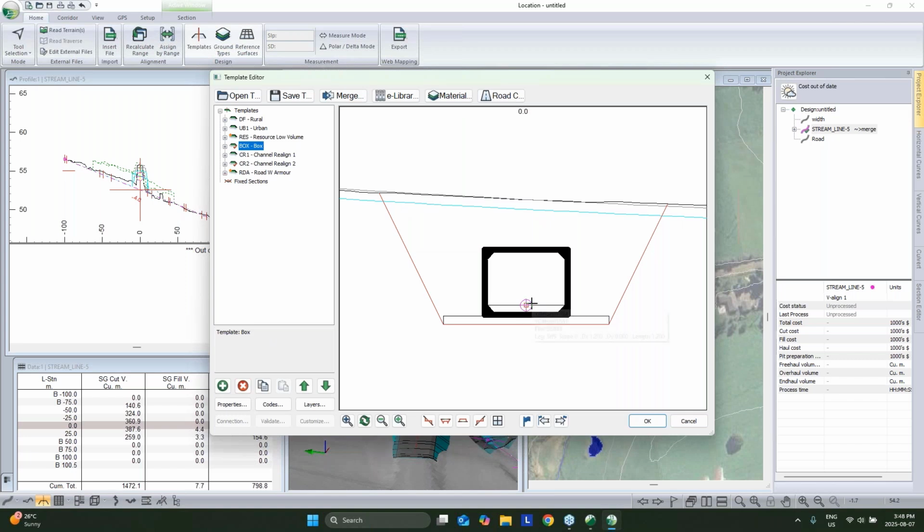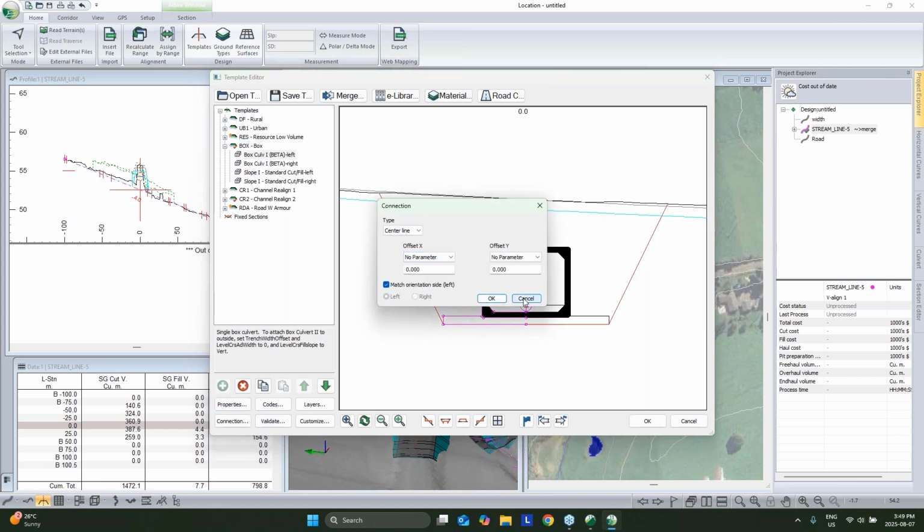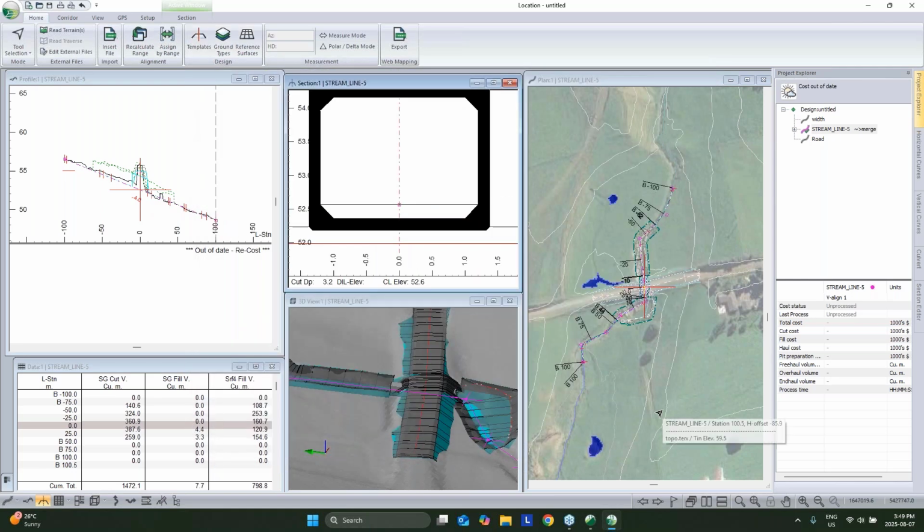So of course, if we want to help ensure fish passage, we probably aren't putting the center line on the bottom of the outside of our structure. So here we've got it embedded a little bit. I've got the box culvert with some backfill shown in there, so that's my center line for this. But if you do want to change your connection point, you can do that, and you could have it offset even more if you like, rather than having to put a jog in your center line profile to show what's being regraded. So we've got our template set up.